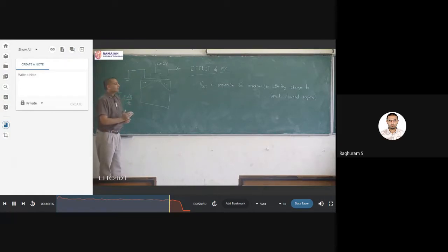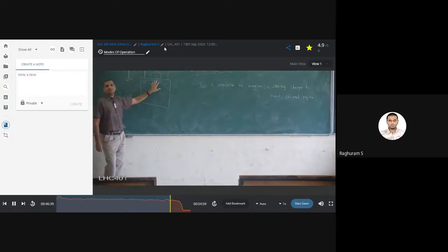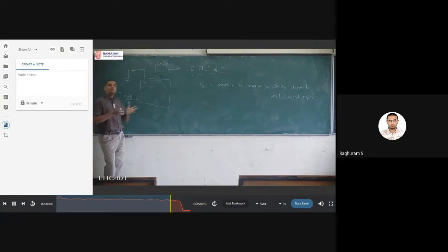But now if they are just sitting, this is going to be 0 because they are not moving. dq by dt, that is the rate of change of charge with respect to time, is not changing. My VGS is fixed at 2 volts. It has attracted some amount of electrons. They are all sitting in this region, but they are not moving. They are all attracted.